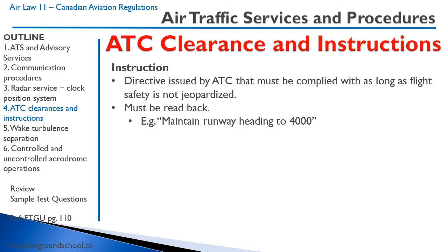on departure, maintain runway heading to 4,000 feet. And I responded, unable runway heading due to the mountain and the fact that it's night. I'd like to make a left turn heading whatever heading I asked for, 3,000 feet. Now, if it was during the day, no big deal. I can see this mountain and I'm probably going to clear it. But I'm not really going to fly towards a big hill at night in a single engine airplane when there's a chance that I'm not going to see something before I can avoid it. So always flight safety and common sense will prevail.